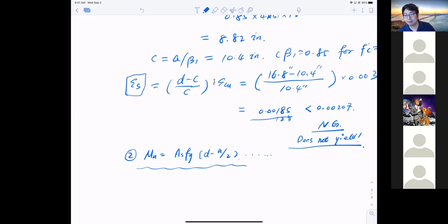Yeah, I understand that. So every time we prefer the steel to yield, okay? So now the mathematical question is: if the steel does not yield, can we use the old equation to calculate the moment? No. No, that's a good question. Good answer, okay? So the answer is no, we cannot use it. Thanks, Marshall. So why can we not use it, right?